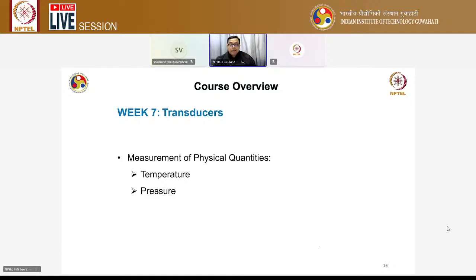So you will see that a simple resistor, say a metallic resistor, can be used for the measurement of temperature over a wide temperature range. Okay, say anything from minus 100 degrees Celsius to over 600 degrees Celsius, and so on. And for the measurement of higher temperature, you can even utilize that, but then you have to change the metallic component and so on, right?